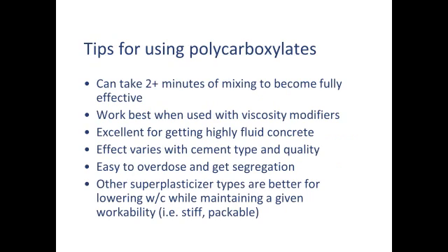Finally, other tips. These take some time. Once you put them in, you've got to mix your concrete for a couple minutes for them to be fully effective, because those polymeric chains have to start working on the cement particles and disperse them. And if you rush the process too fast, you can end up adding too much polycarboxylate, too much super plasticizer. So you have to be patient with it.